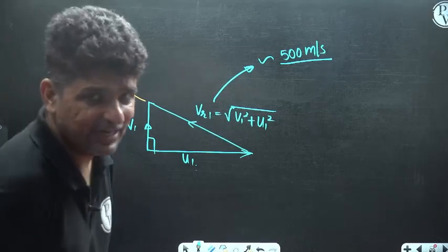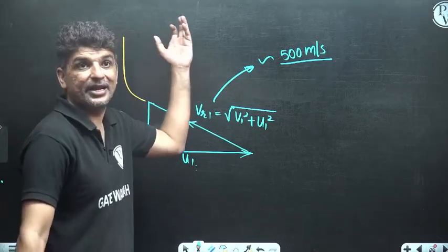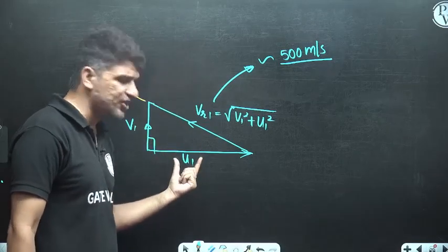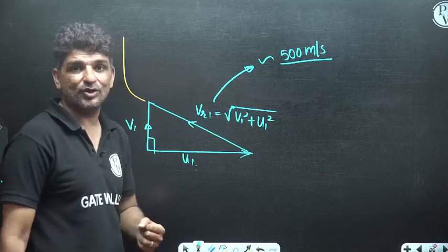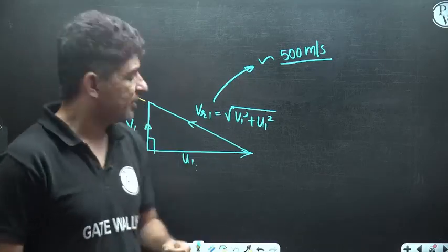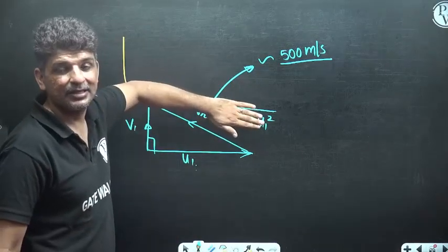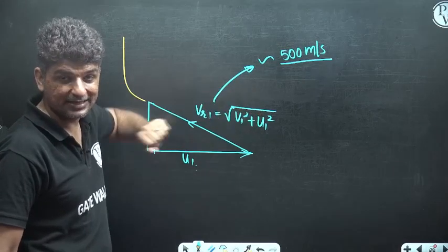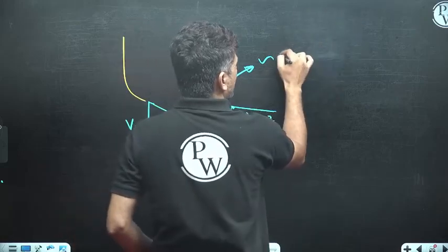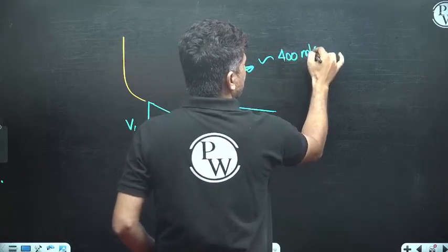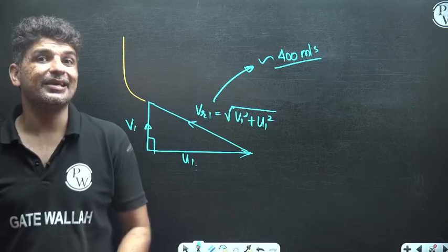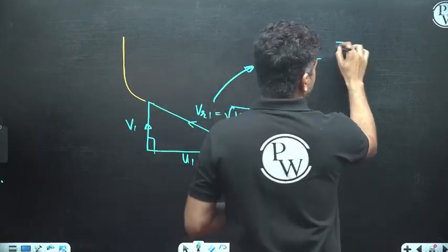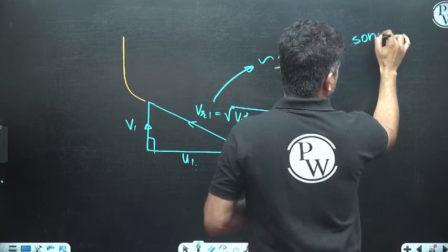Okay, so recently we have seen that the outlet velocities are 392 meter per second, 300 meter per second. So let's say you have this initial velocity as 300 meter per second. Again, this velocity is 300 meter per second. The velocity that you will be getting over here is root 2 multiplied by 300. That is somewhere around 420 meter per second. Okay, so let's say I write this as 400 meter per second. Now you see that this velocity is more than the sonic velocity.